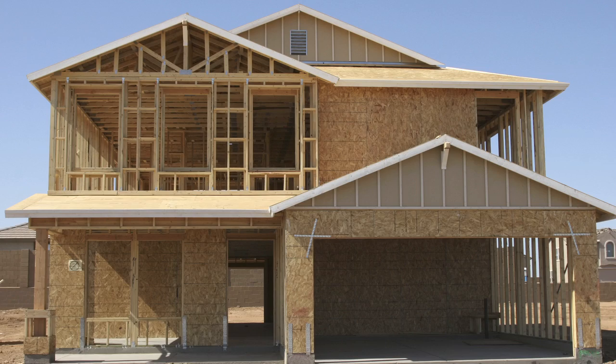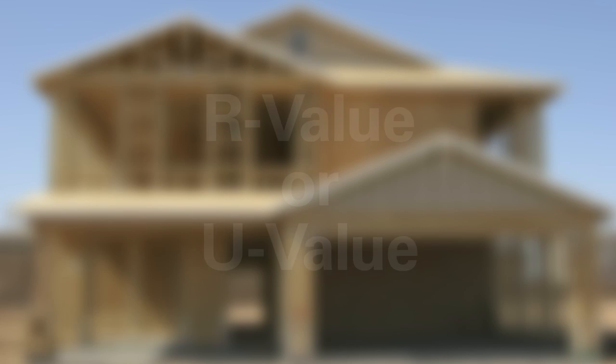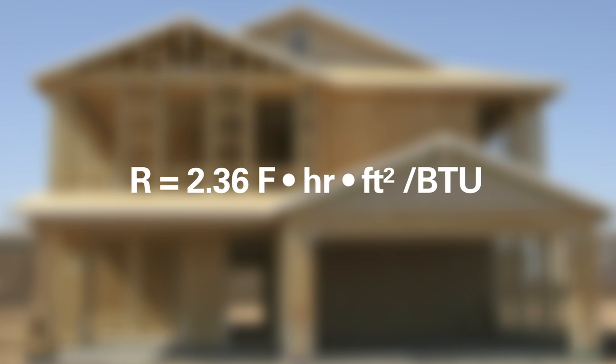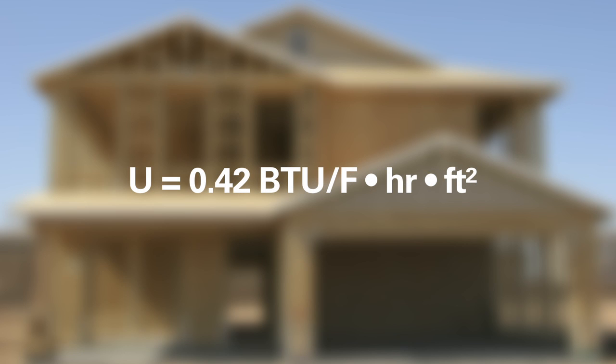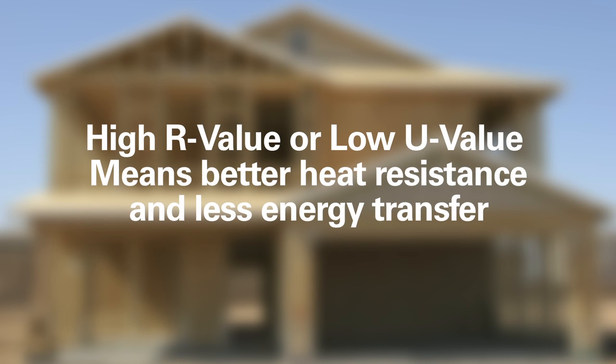Usually, the thermal resistance can be expressed in terms of R value or U value. For example, a double-layer glass window's heat resistance could be expressed with this equation of R value, or this equation of U value. R and U value are reciprocal. Higher R value or lower U value means better heat resistance and less energy transfer.